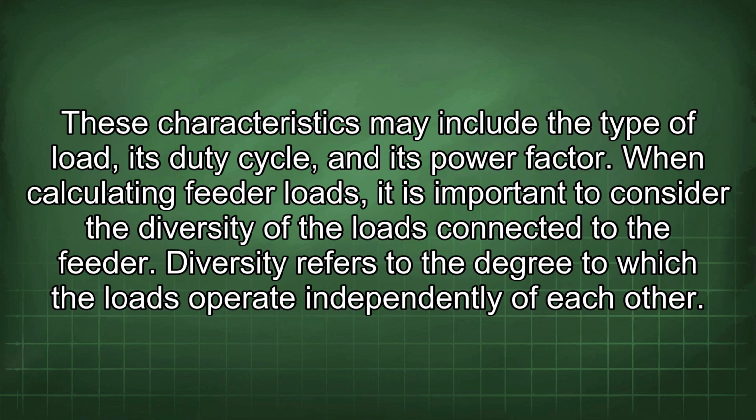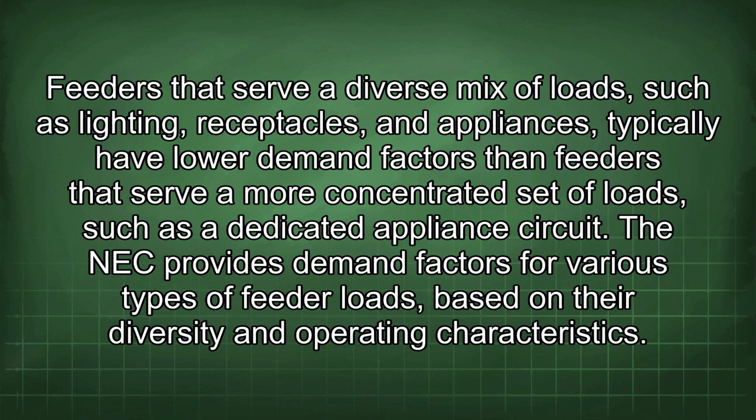When calculating feeder loads, it is important to consider the diversity of the loads connected to the feeder. Diversity refers to the degree to which the loads operate independently of each other. Feeders that serve a diverse mix of loads, such as lighting, receptacles, and appliances, typically have lower demand factors than feeders that serve a more concentrated set of loads, such as a dedicated appliance circuit. The NEC provides demand factors for various types of feeder loads based on their diversity and operating characteristics.